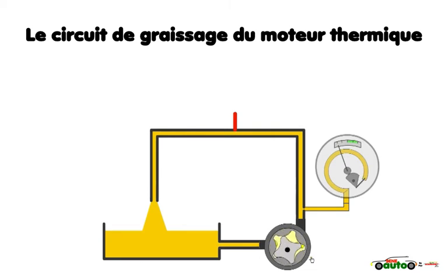Pressure is created when the flow of oil is restricted. We use a Bourdon pressure gauge to indicate oil pressure. When pressure in the tube increases, it tends to straighten, and this change in dimensions is amplified by the linkage and gears and displayed by the pointer on the dial. If we close the valve, the flow of oil is restricted and we start to build pressure. If we close the valve further, we see another increase in pressure.